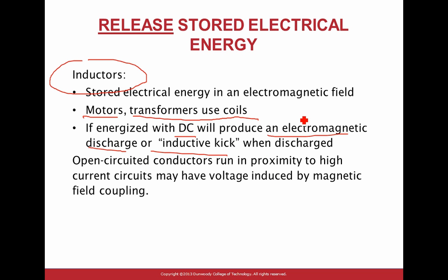And if you have low voltage, that's why the NEC code book requires you to put your low voltage conductors in a different conduit or cable than high voltage. If you put a coaxial cable right next to the power cable, the higher voltage will induce voltage into the lower voltage, and you could have a shock from the induced voltage.